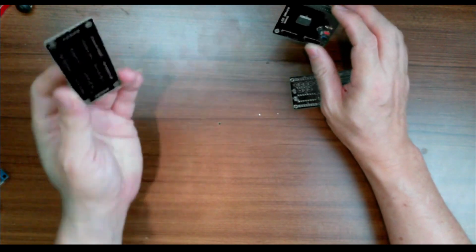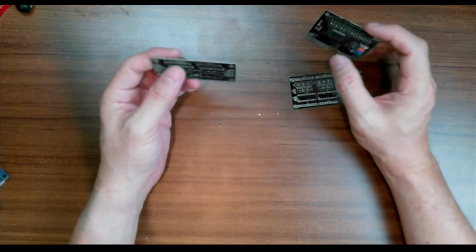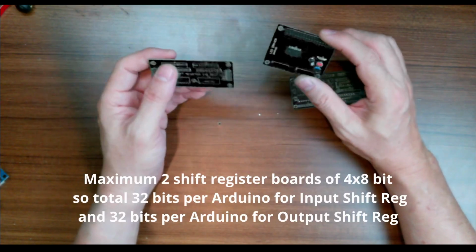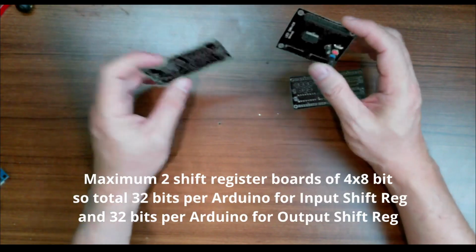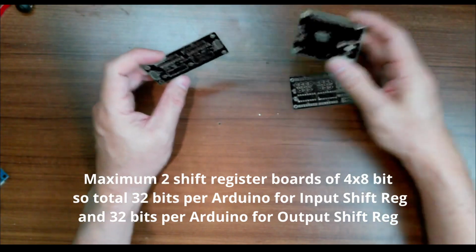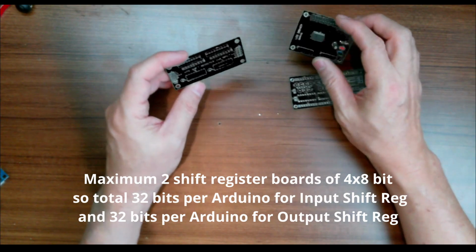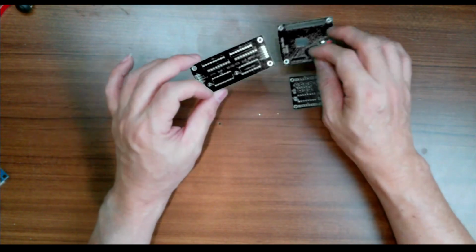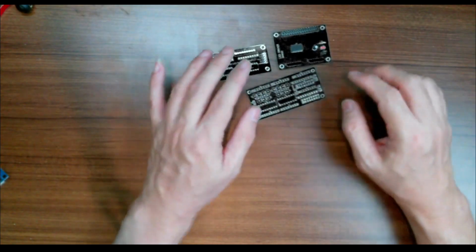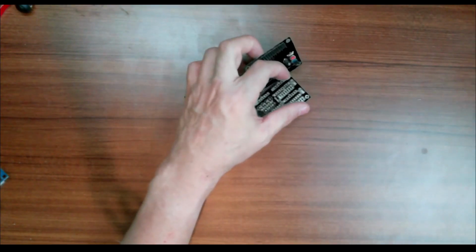Or actually only 2 and 2. I forgot. But anyway, MobiFlight is limiting its ability to drive shift registers. Like MMJoy can drive many of them in serial, but MobiFlight is limiting to 3 or so, I forgot. I'll have to check again. But anyway, this is how I drive the LEDs, and how I get the input from the switches.